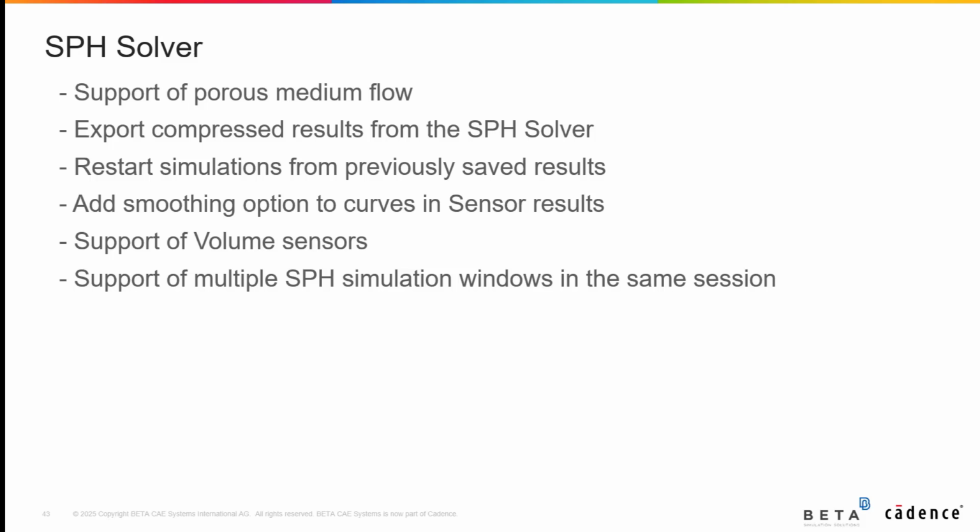Additional improvements for the SPH solver include support of porous medium, export of compressed results from the SPH solver, restart simulations from previously saved results, new smoothing option to curves in sensor results, support of volume sensors, and support of multiple SPH simulation windows in the same session.